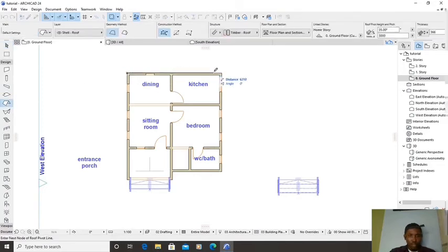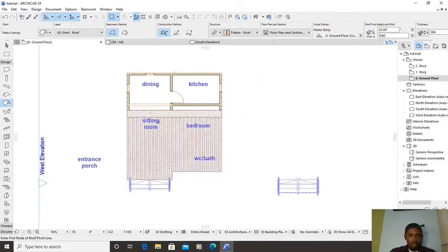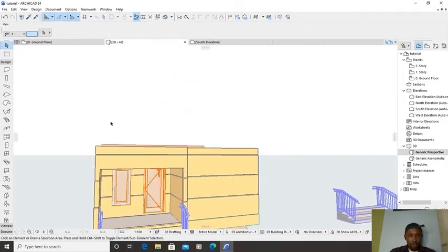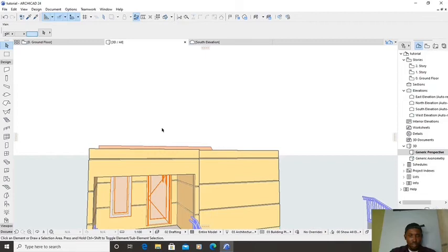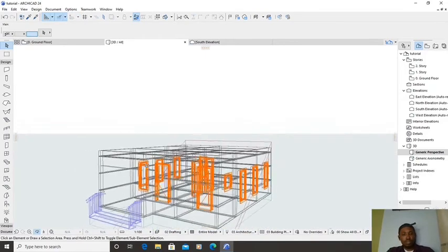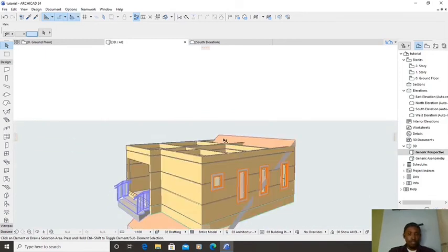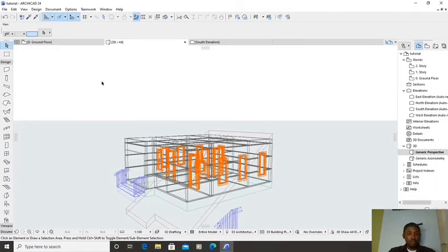Okay, let's start from behind so that the roof will actually slope towards the back like we want it. Okay, pick all the edges, and drop. Okay, let's see if we have what we need, right? Right now the angle is okay. Press zero on the keyboard. Okay, nevertheless, it's still giving us an opposite angle.